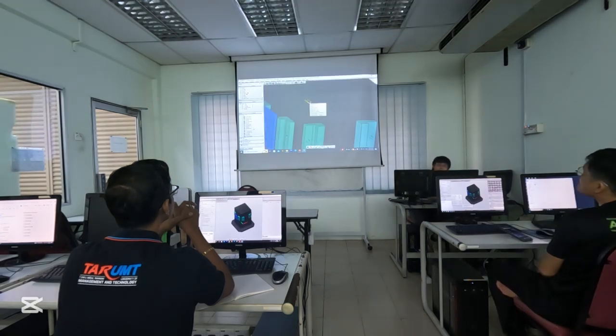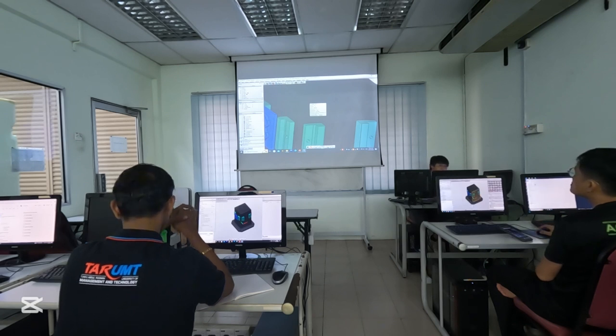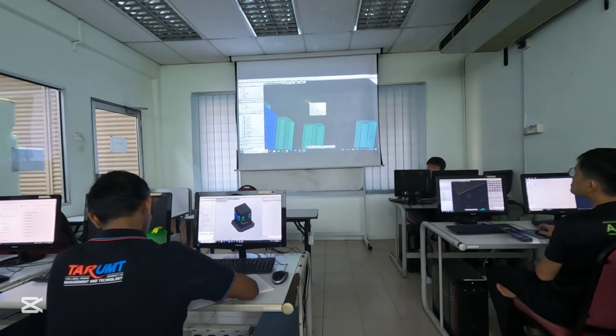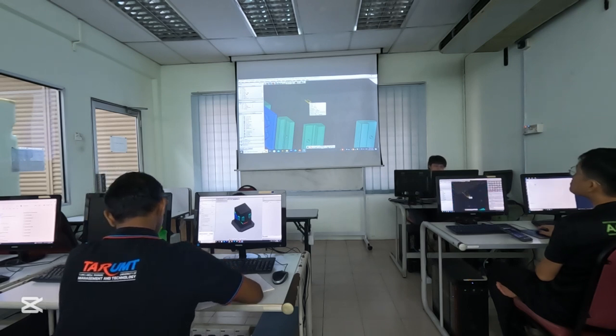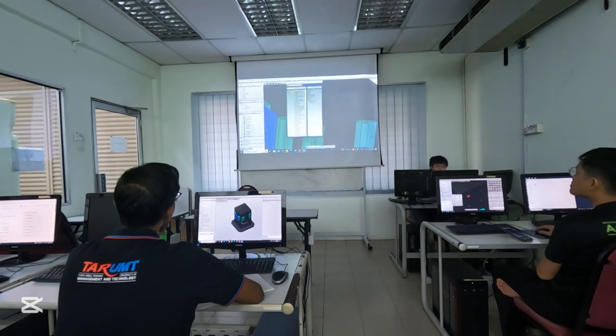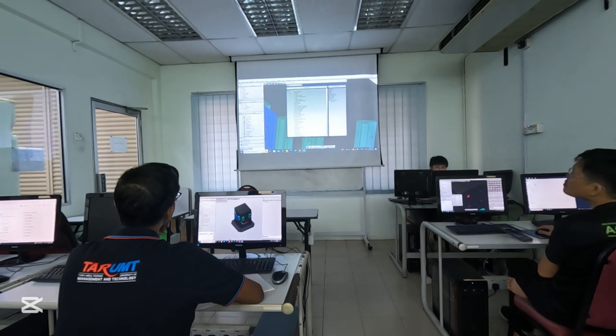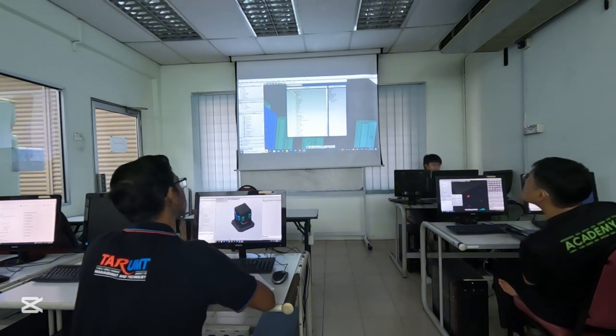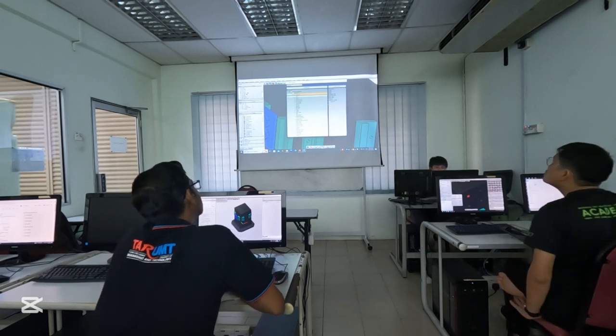So you can try to move your cursor to an object. Mine has already changed last time. If your object shows the radius, amplitude, diameter, area, and all that. If your screen doesn't have it, you can press File, Options, Tooltip Content, and then this Measure, if it is still in default, this Measure will not be here. Then you can add in measures and drag and drop it.